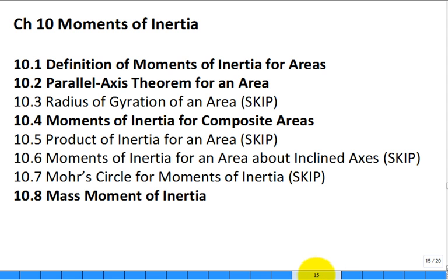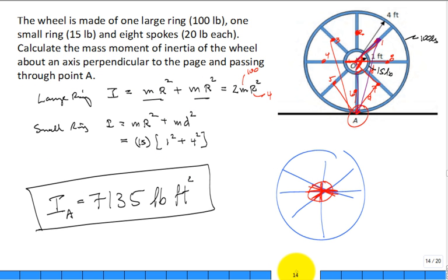Yes? Sorry, just if you're going to do that second way, how much would each rod weigh? 40 pounds? Oh, no. Yeah, you have to figure out what is the density. So we have 40 pounds in 6 foot of actual. And so now you have that ratio. Now I don't have 6 foot, I have 8 foot, right? So then I'd multiply by 8 foot, and so each long rod would have more than 40 pounds.